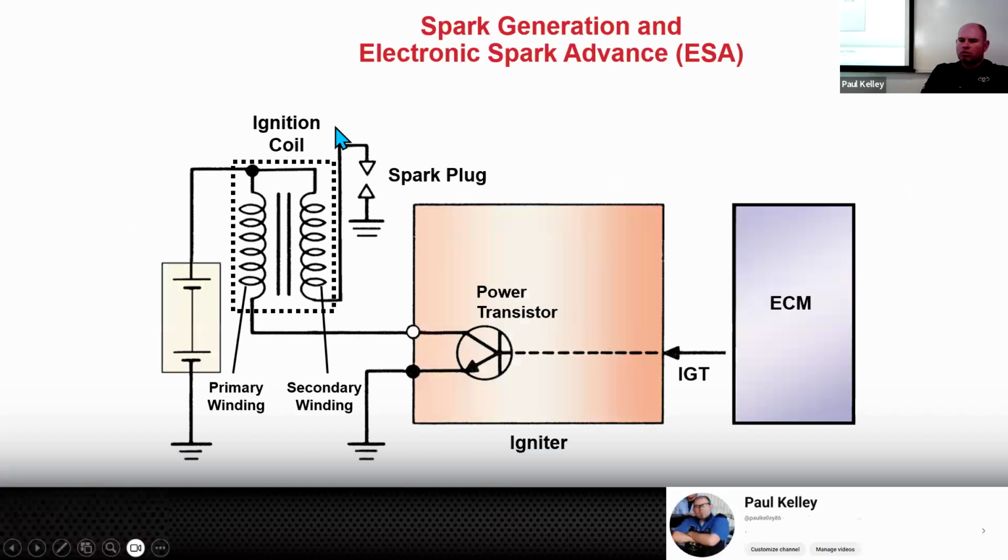And then when we get into that triggering thing, this is a Toyota-specific slide, but I really like it because it helps people to understand. This is your coil right here. Actually, this whole thing is. A lot of times on the newer ones, the coil will have the triggering device inside of it, which means it just has to get a signal from the ECM.